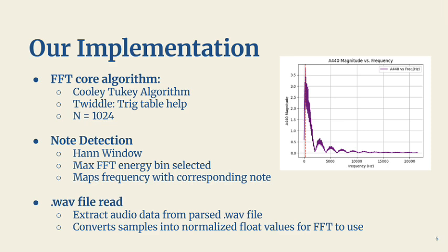Next, for note detection, we first apply a Hann window. This is a functionality that helps to smooth the audio frame and reduces spectral leakage, which makes the FFT output much cleaner.